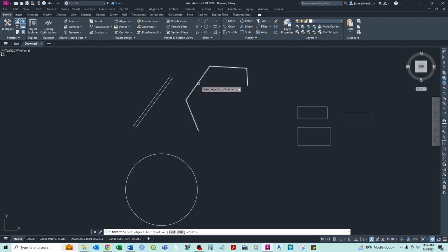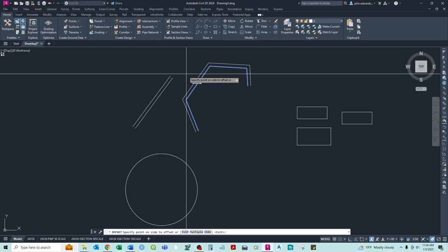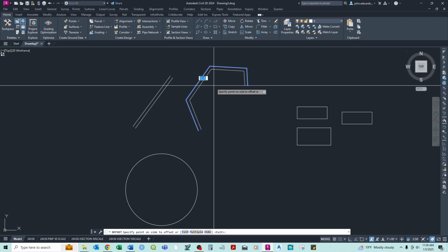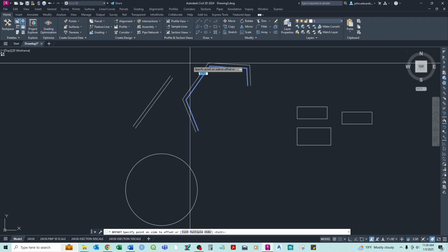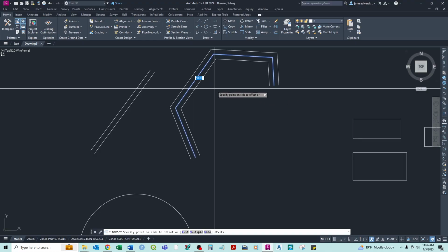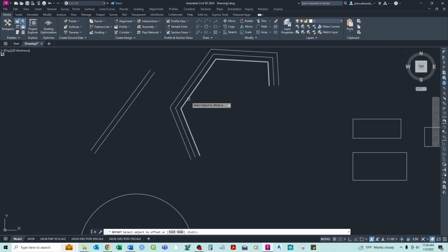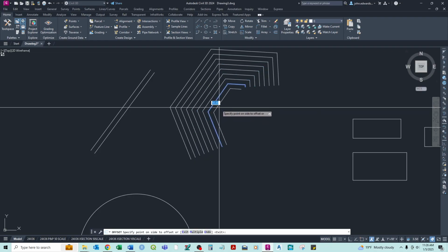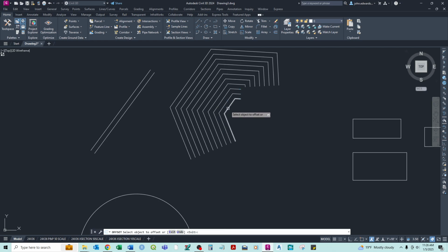For a polyline, we can do the same thing, and we can offset it to the outside or to the inside. But you'll note, when it goes to the outside, this line is actually a little bit longer than when we come on the inside, because it's offsetting an exact distance. If we kept offsetting, this thing becomes smaller and smaller, because the distance is maintained exactly, all parallel.